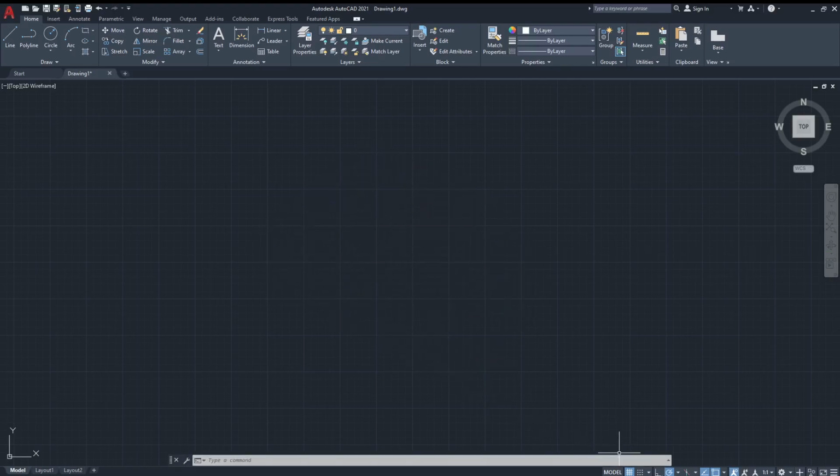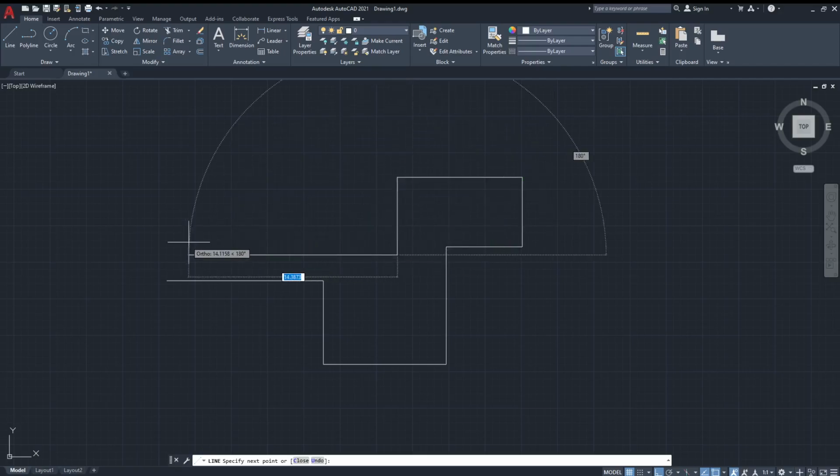And there is this other mode as well called ortho mode. If you would like to draw just 90 degree angles, for example, if you would love to do just horizontal and vertical lines, this mode is for you. For example, you have a shape that's like this. Let's choose a line. All you have in this shape is horizontal and vertical lines. I would command you to use this ortho mode. But if you would use the other mode, it will just make your life harder.